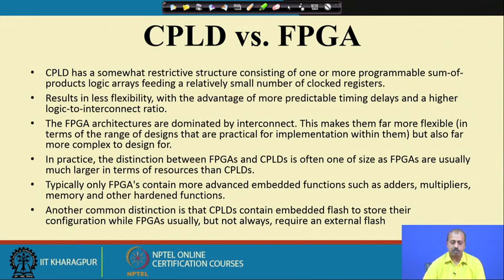Typically, only FPGAs contain more advanced embedded functions such as adders, multipliers, memory and other hardened functions. So, what I mean is that if you look into advanced FPGAs now, you will find that there are built-in adders, built-in multipliers, and memories available, because if you are trying to make a system, apart from this logic element processing, you will require some amount of memory, and many times we need addition, subtraction, multiplication, division type of operations.